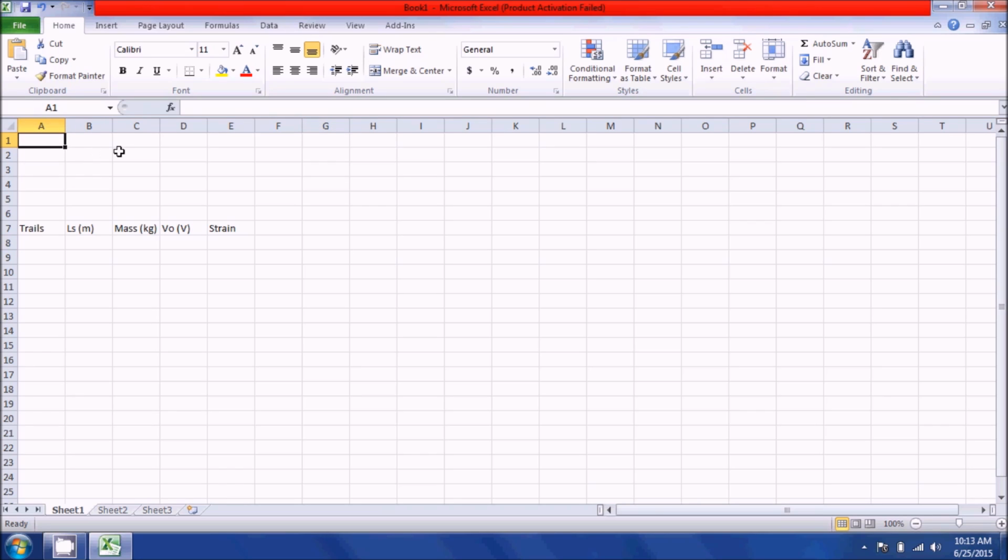Now we need the initial voltage, the excitation voltage, and the gauge factor. For this lab we use VEX as 5. We used a gauge factor of 2.05. Remember, VEX is voltage, so it has units of volts. And then the last thing we need is VI. This is the value that LabVIEW gave you for the initial voltage after you calibrated the strain in the settings window. For me, I'm just going to use 1.5 millivolts, so that's 1.5 times 10 to the minus 3.